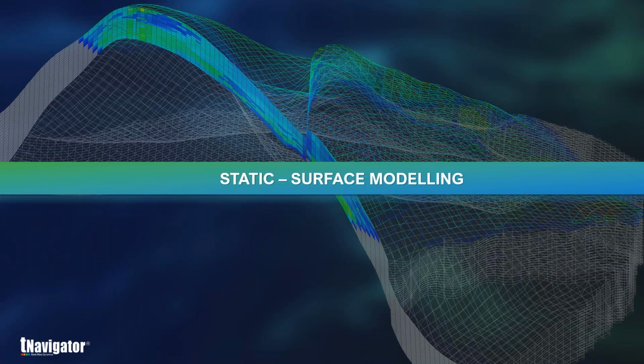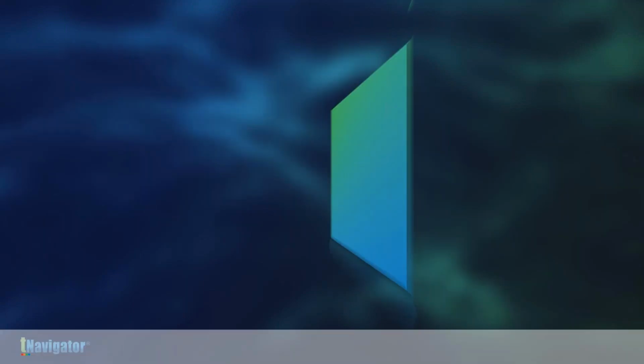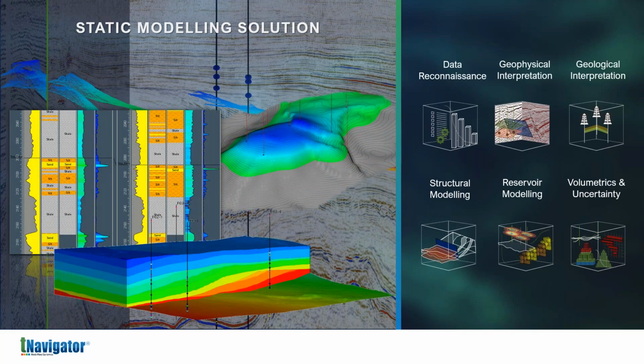Now we will go through each of these steps and milestones, and we'll see how these can be achieved within tNavigator itself. So we'll start with the static modeling side of things. We started with the data reconnaissance or data gathering, where seismic images, data from samples, logs, etc. can be loaded into the project. If seismic's been added, it can be tied to wells, depth converted, and further manipulated to allow surfaces to be interpreted, which will ultimately detail units in the geothermal reservoir, which can be then played with.